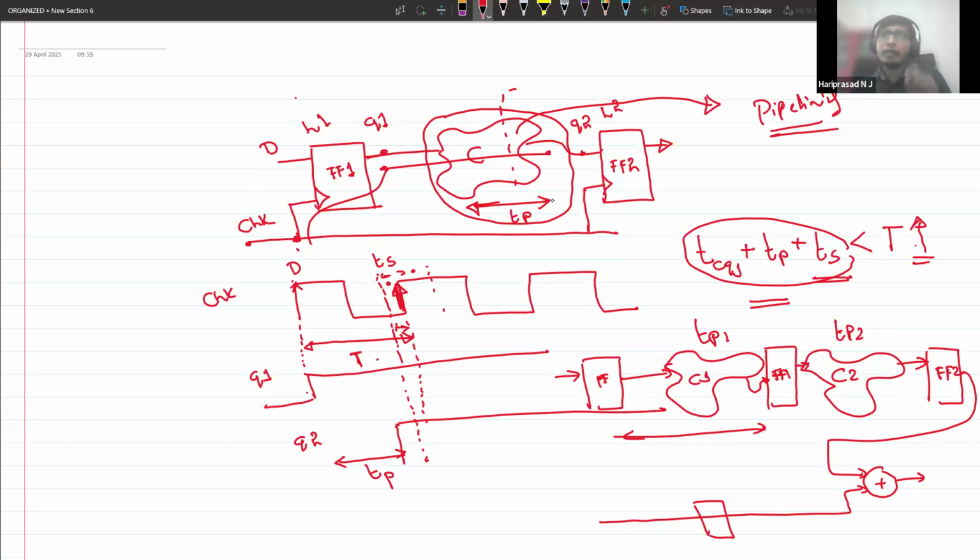And you are introducing latency also. Previously, you were expecting this output after the first clock, one clock cycle. Now the latency became two clock cycles. This is a trickier thing, so you have to carefully handle it. But this latency is only at the startup point, right?